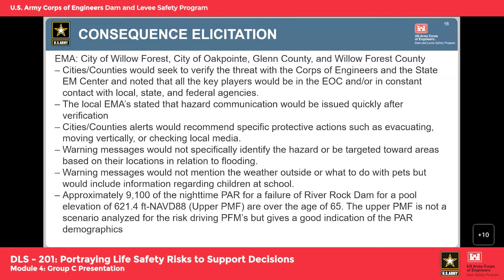I know this slide's pretty wordy and goes over a lot of the communication that happened between the different groups. But one of the key takeaways we wanted to point out was the approximately 9,000 PAR for the River Rock Dam pool for the nighttime failure modes. That's using the upper PMF inundation. A significant portion of those people are over the age of 65, so evacuation is a little bit more limited. And next slide.